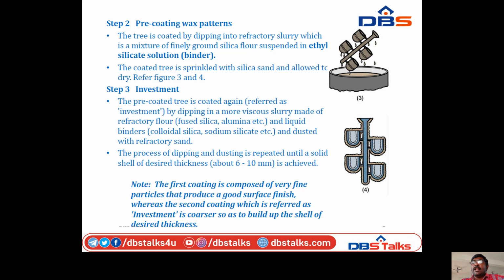Note, the first coating is composed of very fine particles that produce a good surface finish, whereas the second coating, which is referred to as investment, is coarser so as to build up the shell of desired thickness.